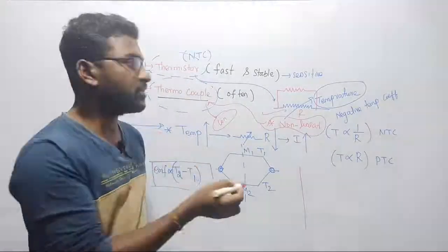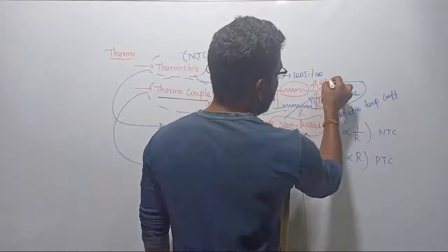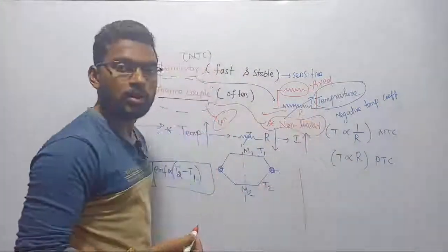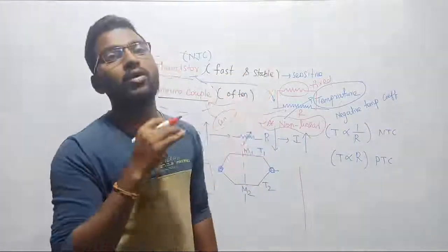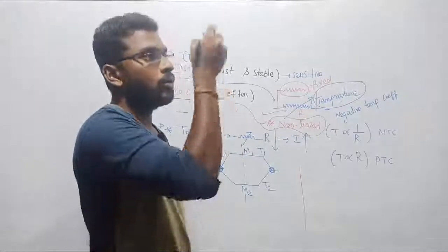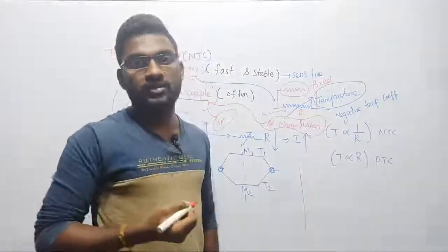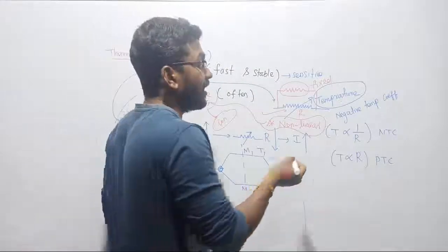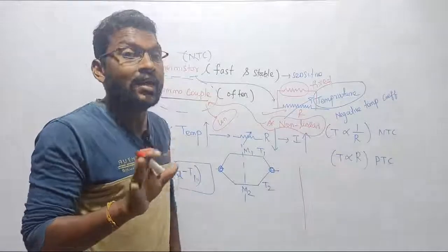If we put in the derivations to prove it, this resistance is a fixed resistance. By connecting a fixed resistor across the variable resistance, the circuit becomes a parallel resistance, and when we put in the equivalent value, going from one value to another there is no big change in the value of the resistance, right? So such that non-linear behavior can be improved, right? Listen guys, it cannot be eliminated.